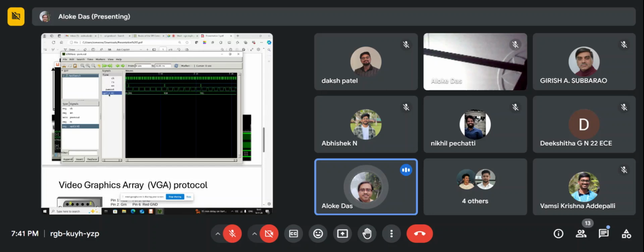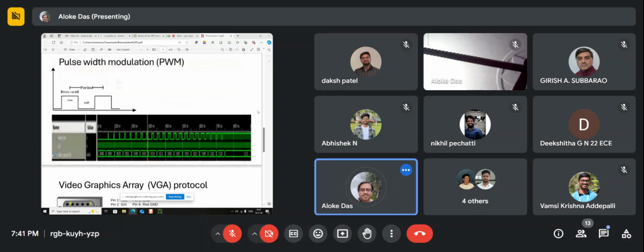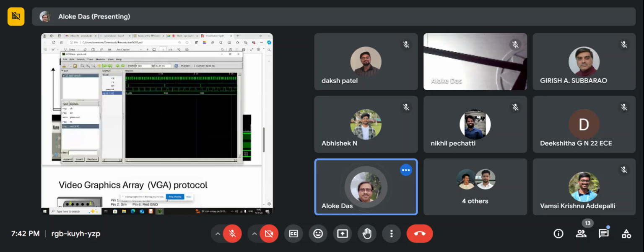Otherwise, when I want to change the uptime, that uptime has to be synchronized with some signal. Then I had to add this enable signal. But in the discussion, there is nothing called enable. So just make note of that. Whenever you go to implement, you might see you need more signals than the specification has. So that is one very interesting thing.